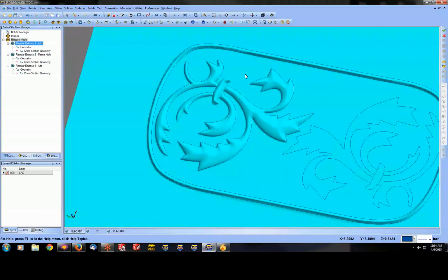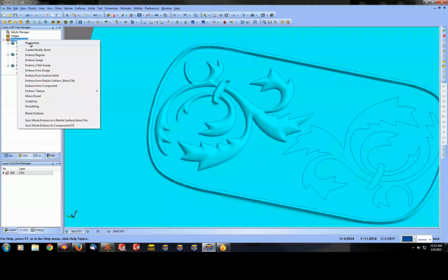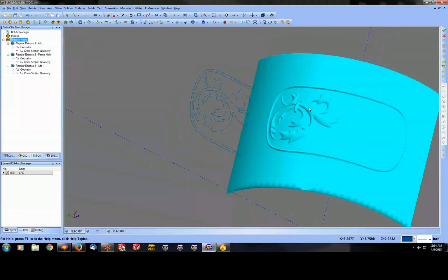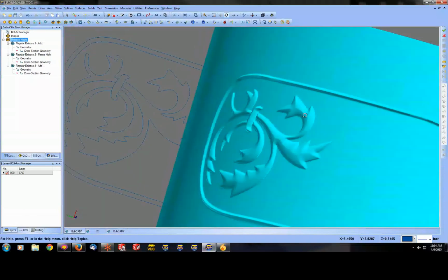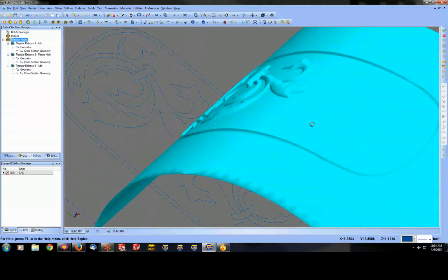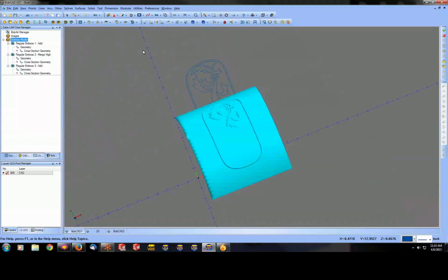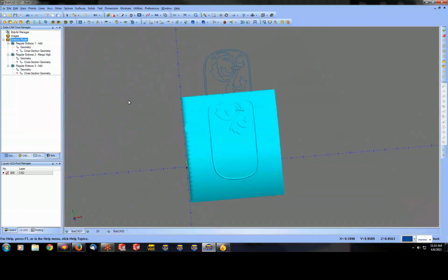So we can go through and add that to a machining job. Now you can even go in here and add that to a wrap, where you wouldn't really be able to do an unwrap with that because it's 3D geometry. So we can go in and modify the stock, put in our full cylinder value as 12. Then that puts our geometry on that cylinder as the 3 different levels, giving us a little bit more embossment out of it.